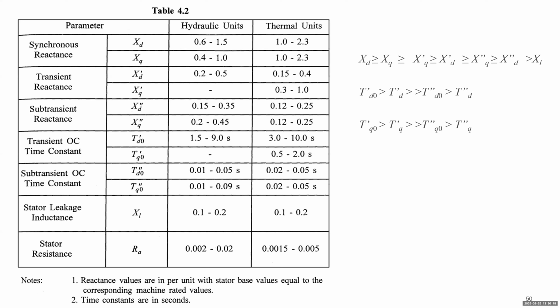For instance, you get some power system model with a very low order, classic model, but you want the generator to present more interesting dynamics. You want to add sub-transient or transient dynamics, but you miss those data. If you have a very classical model, very likely you have this one or maybe that one, but based on this range, you can also create the X double prime or T double prime.